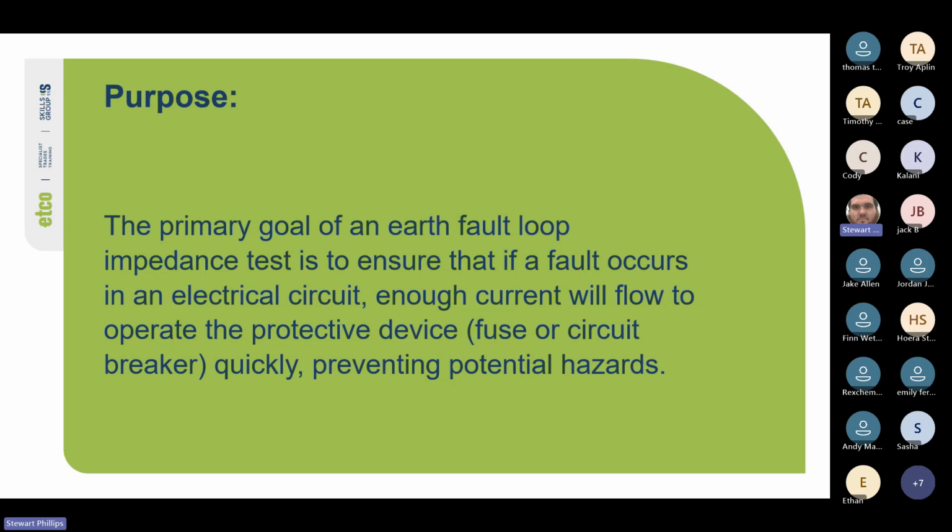The windings in the transformer form part of the fault loop, and because they are wound coils, they generate a magnetic field when current flows through them. So in the event of a fault, the sudden surge of current and the frequency dependent nature of the magnetic field introduces inductive reactance into the loop. So that's why we need to be doing a fault loop test.